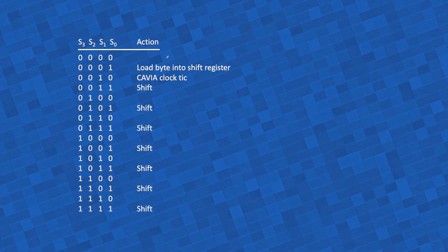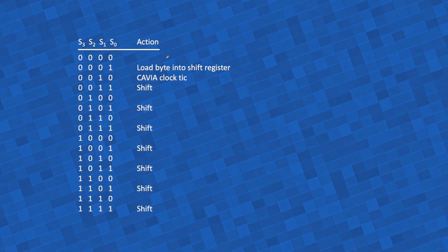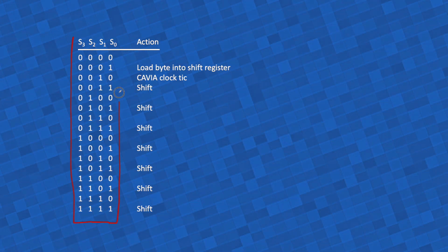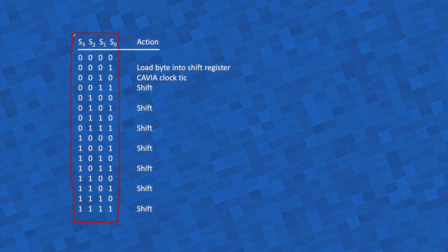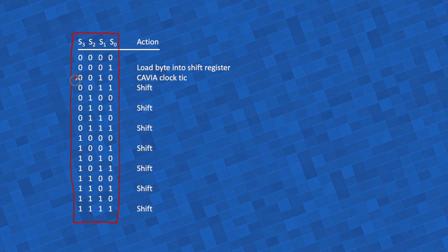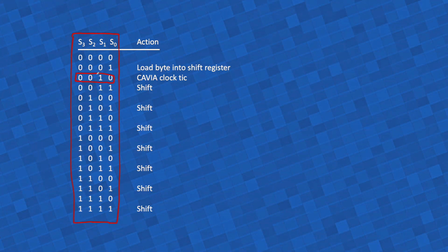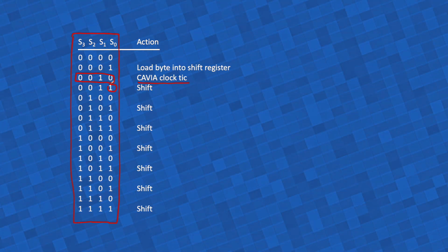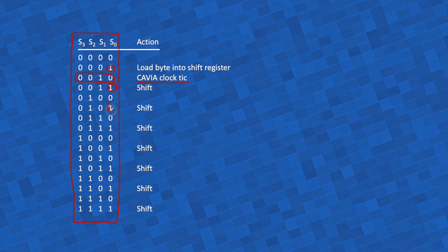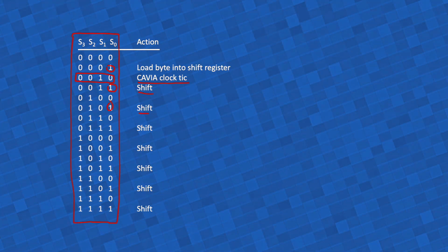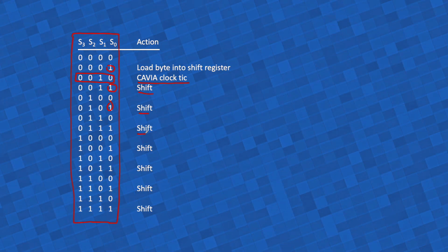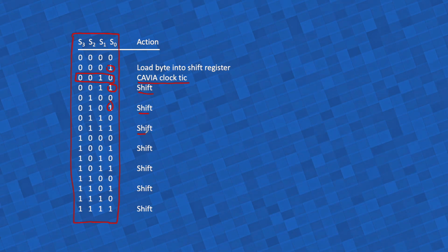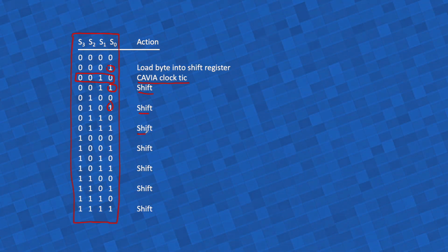And note, there are no monostable states, no delay lines, we simply use the states of this counter as a little state machine and clock divider. Clock divider because, for instance, if we take only one of these 16 states, we get the Cavia clock at 1/16th the frequency, and if we take only every second state of the 16, we get the shift register clock. So this counter is at the same time a clock generation circuit and a little state machine that does that.